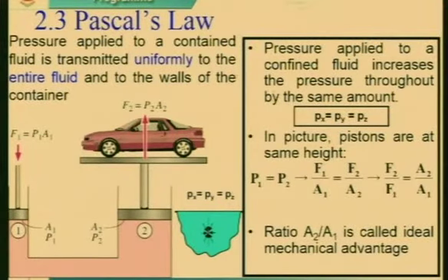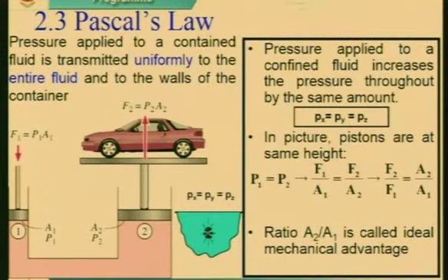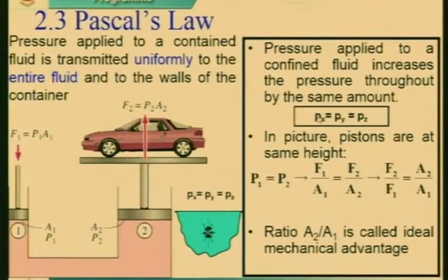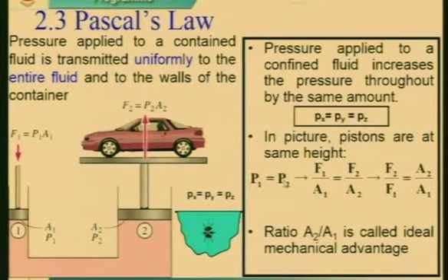So, definitely this is very important. It says that pressure applied to a confined liquid increases the pressure throughout the fluid by the same amount. It means the intensity of pressure Px equals Py equals Pz at that particular point. It is called Pascal's law. This concept is being used in the hydraulic jack. You might have seen a car jack, where they apply a very small force. Similarly, in hydraulics, P1 equals P2, that is F1 by A1 equals F2 by A2.